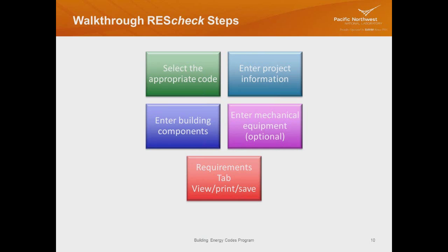The next thing is that you'll want to enter your project information: the location of your project, the city or the county, who the builder is, if that's applicable, and any of that information in the project area. Then, before you start a REScheck, you're going to want to have in front of you all the specs, the construction specs.